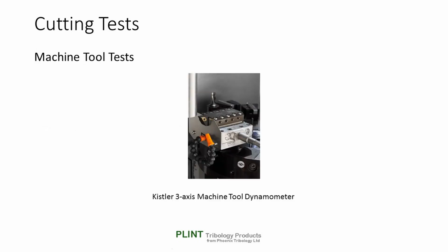In many cases, full-scale CNC machines are used for evaluating drilling, tapping and machining processes. Tests invariably involve the consumption of large quantities of workpiece materials. The machines may be instrumented with standard machine tool dynamometers to allow measurement of forces.